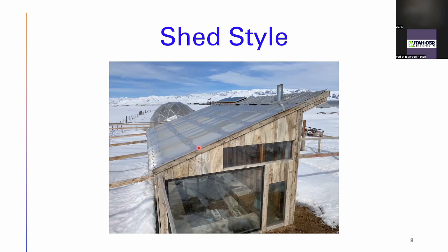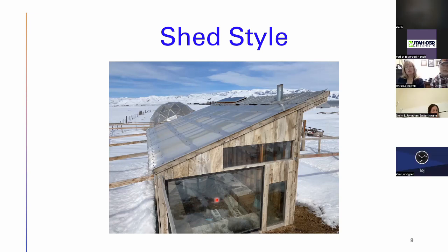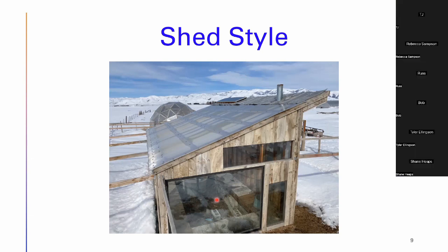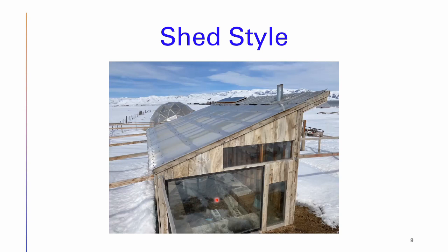You could have all the neat ideas on the planet. So I have a rocket stove in here. I'm recessed. I had an insulated north side. All the ideas that people do. And what was impressed upon me is those things are so negligible in terms of providing the energy for a greenhouse in comparison with glazing and structure, your architectural design. Those two items, your architectural design and your glazing, are predominant. You have to get that right before adding any of the other peripheral stuff like ground loops and water containers and stuff like that. You have to get your design right.